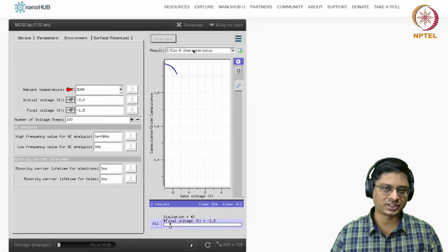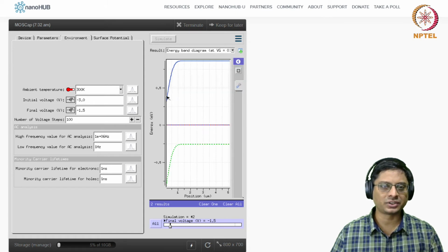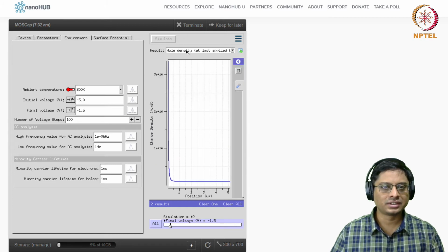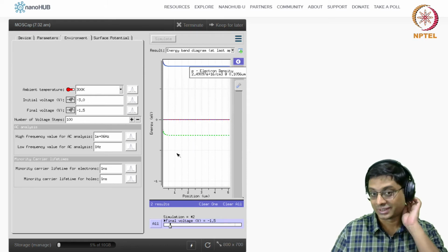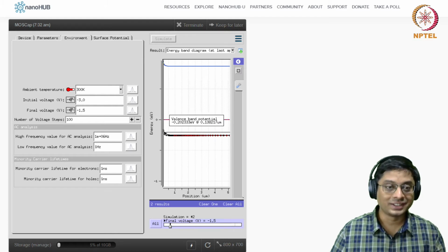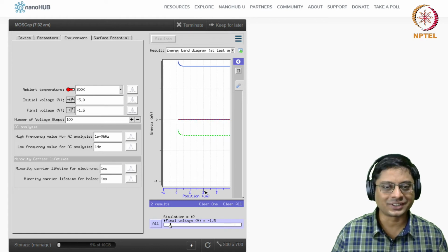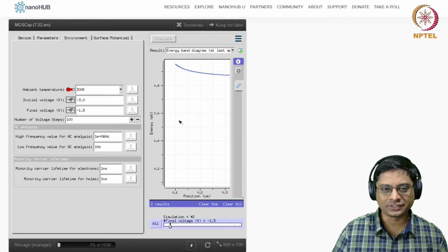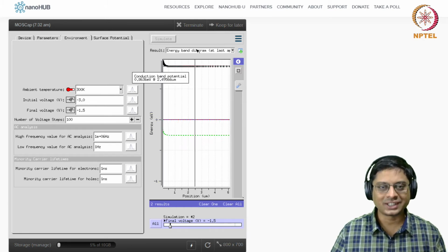All right, so it just started depleting. Let's see, how do I know that? Well, with no gate bias, there's already some depletion. But if I look at the last applied voltage, let me look at the bands. Well, okay, no, I'm wrong. At minus 0.5, you see I'm actually still accumulating. That's why this is interesting. You can correct yourself. I was thinking that it's going to be depletion, but it turns out that it's still accumulation. So the EF is closer to EV, so it's accumulation actually. Let's see, it's an interesting thing.